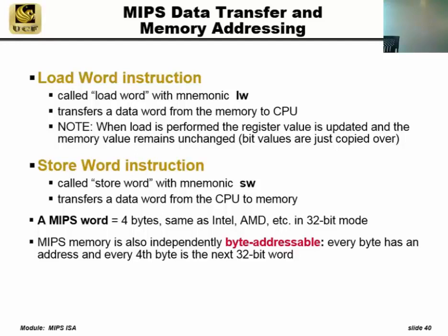If we use a load word instruction, which is one variety of load, 32 bits gets returned. Why? Because in MIPS, each word is 32 bits. We're going to see in another slide, there's something called load byte. Load byte means I transfer a byte. They actually use lowercase b, sorry, but that's how they did it. That means 8 bits is transferred back from the memory to the processor. So that's what we're going to look at today.